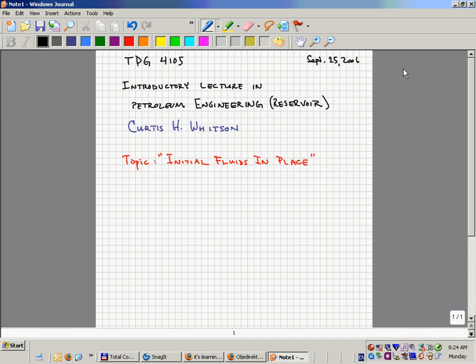And with that driving potential, in Ekofisk, it's a little bit special because the chalk has been broken up into pieces about the size of this table. So the flow doesn't have to flow only through the rock itself, but there are fractures, or small sprekker, between each of these table-sized blocks, or maybe sometimes the size of a room. So most of the actual flow is going through that network of fractures. But the rock itself, the permeability is about 1, and you don't get much flow through that unless you push hard.